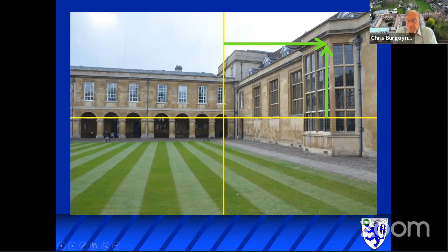It depends on how the lens is set up, so that needs to be computed. And therefore you get measurements of where something is. As a comparison of accuracy, 1 pixel on this image is the equivalent of about 40 seconds of arc. So it's 4 times less accurate than a theodolite would be.